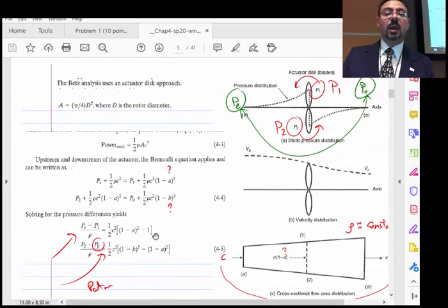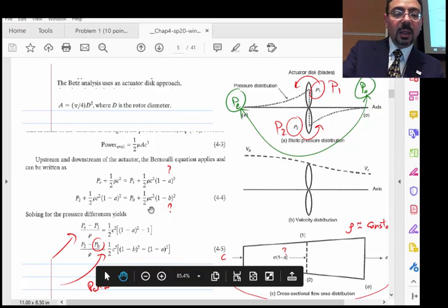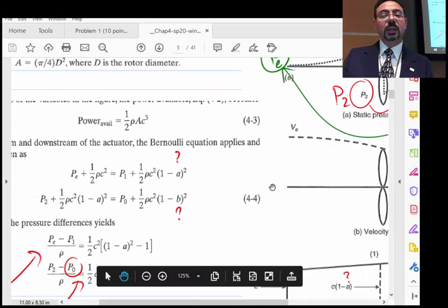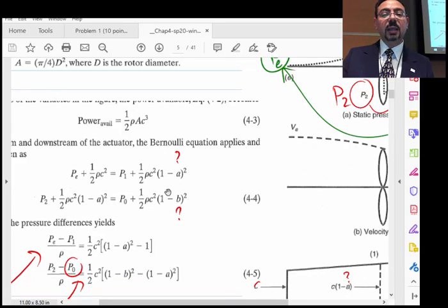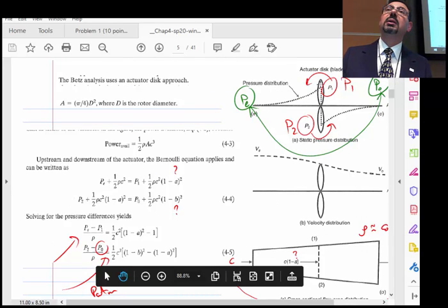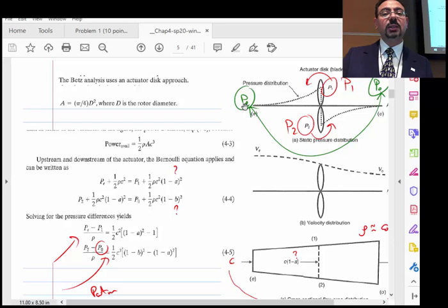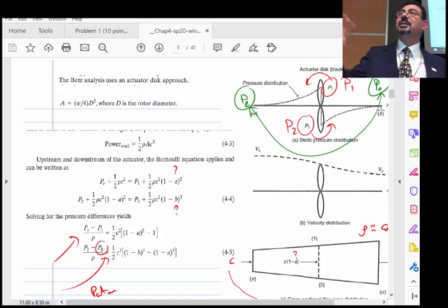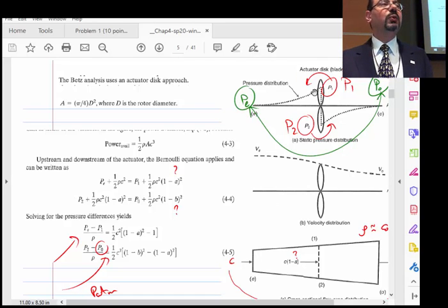So he is going to apply the Bernoulli equation between the entrance and point 1. What is point 1? Just before the disk. Can we say that the energy here equals the energy all the way at the exit? No, otherwise why does this turbine exist then? The energy at the inlet is not the same as the energy at the exit. But the energy here and here, just before the turbine, is the same. And that's what you are seeing over here.